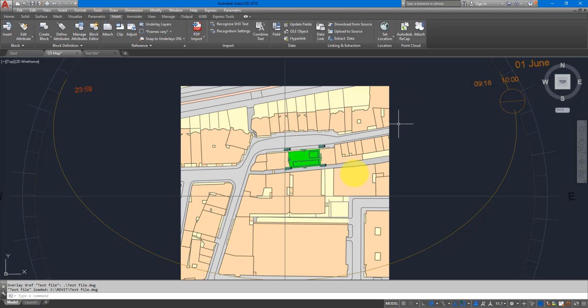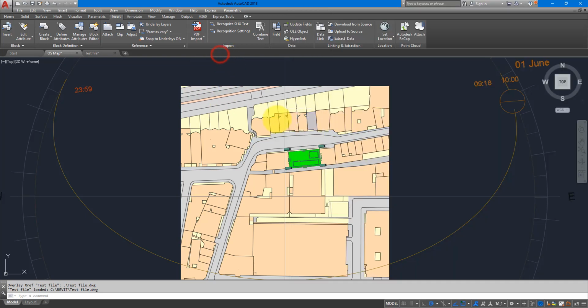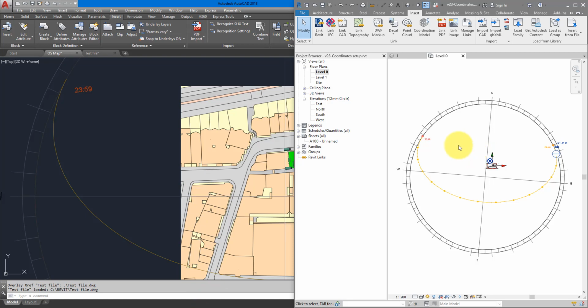As a result, I can now confidently go back to my Revit file and try to link this CAD file in. Also, there's a reason why we had to do those several checks in AutoCAD, because when you bring this CAD file into Revit, other problems can happen, and usually the problems should have been fixed in AutoCAD. That's why we always have to go in here first, make sure the alignment is correct, make sure the coordinates are right, before you even try to attempt a link into Revit. So it's time now for the finale. Let's go to Insert, and then Link CAD.